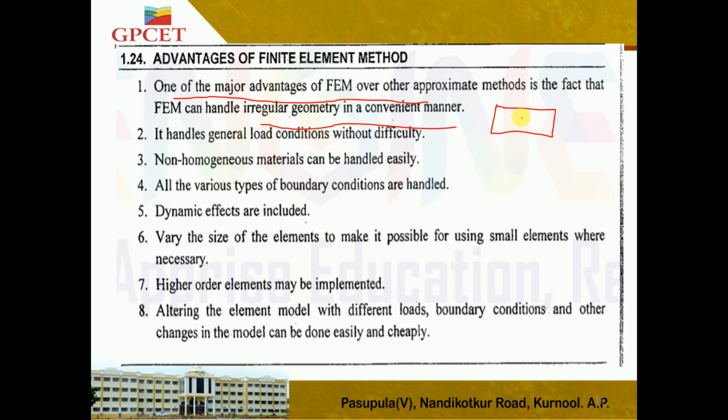Mechanical students will get this kind of problem, a thin plate with a hole, where we apply some forces and get the stresses, principal stresses, principal strains, everything by using FEM. So FEM can handle irregular shapes also, like this, over other approximate methods.